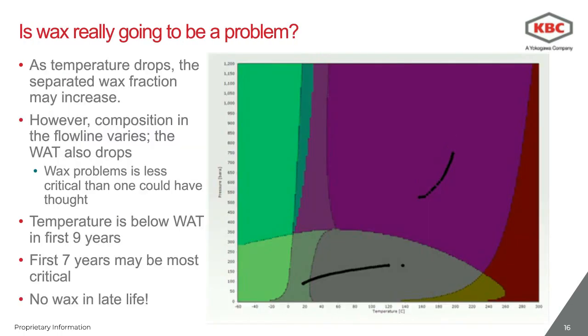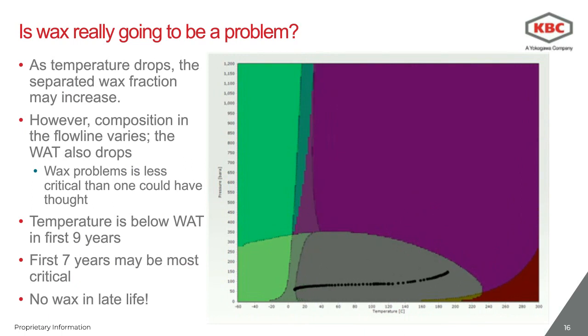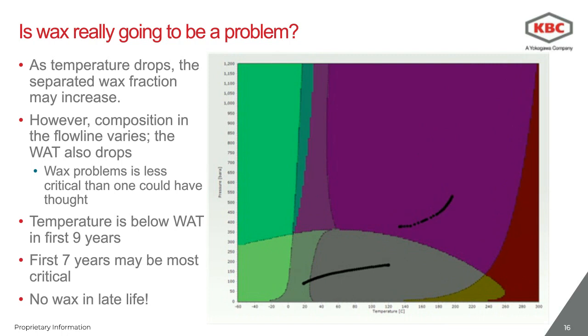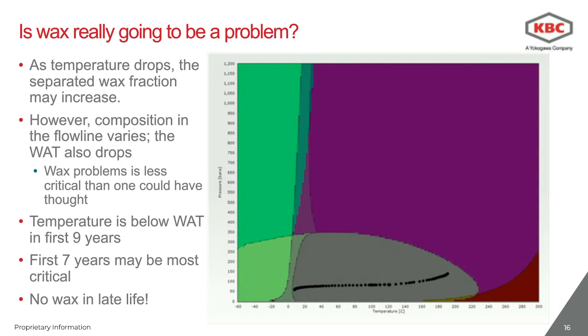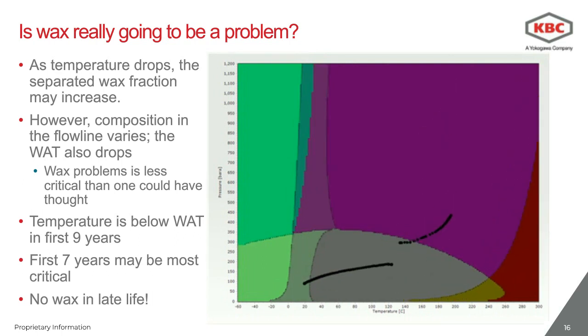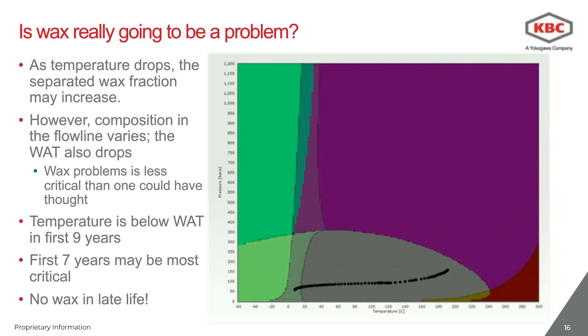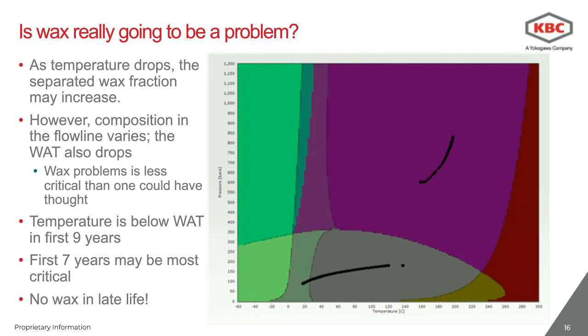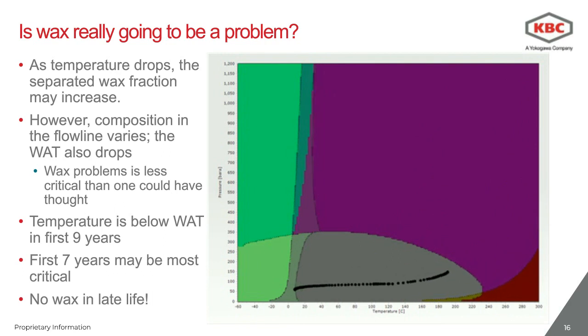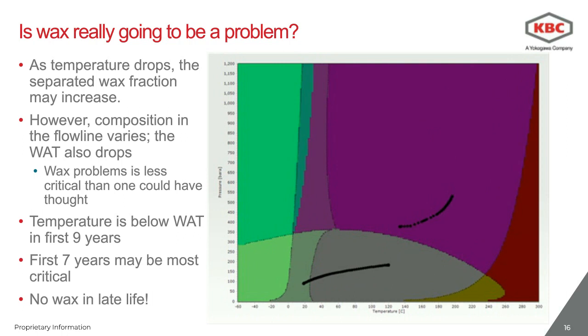And to have a complete understanding of what's going on, I need to now compare everything with the phase diagram again. Let's concentrate for the moment on the moving profile that you can see, the black dotted line that is moving in this animation here. This is representing the pressure and temperature profile for the whole production line. This is particularly looking at well 1, but it will be similar if we looked at well 2 or well 5. You can see that the part with the higher pressure, which is dropping, is the subsurface part.